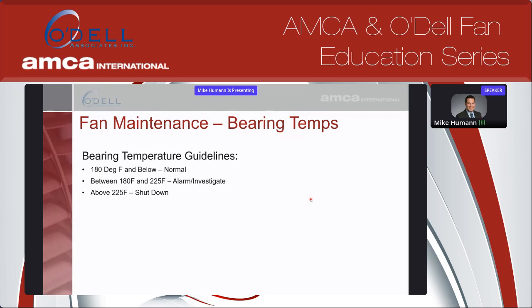Once you start to see it creep up to near 200 degrees, or about 100 degrees C, you're really going to want to start to investigate, and you likely have a shutdown alarm at about 225 degrees to figure out what's going on. And like I said, when you first grease a bearing, it will run a little hotter. So you may want to watch temperatures afterward, and if it is running hot, make sure it starts trending down and normalizes again after re-greasing. And like I said, anything above 225 degrees, you really want to shut it down and see if you can identify the problem.